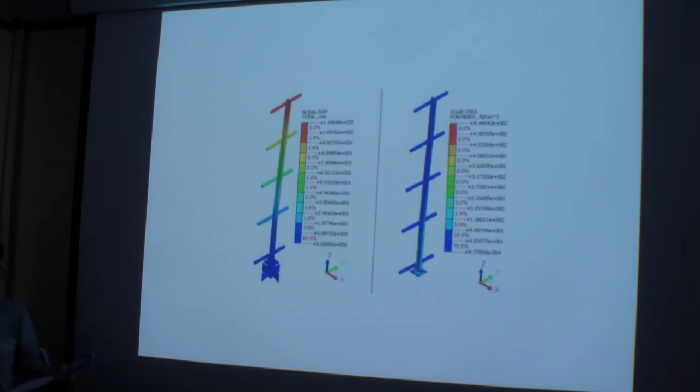On the other hand, for the bolted type case, the maximum displacement is 10.81, and the maximum stress is 98.20 megapascal. The stress ratio to yield stress is 35.7%, which is the same as the previous one.